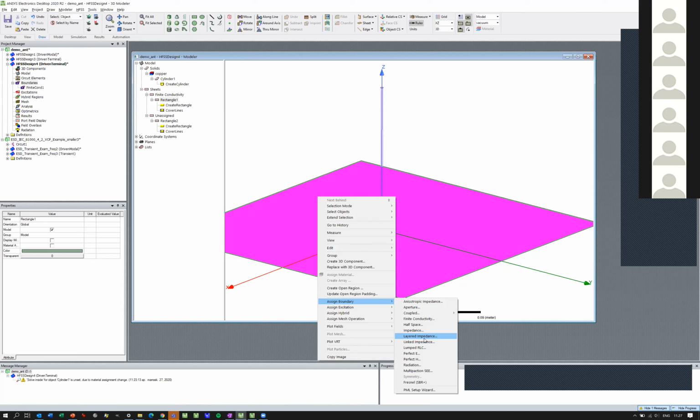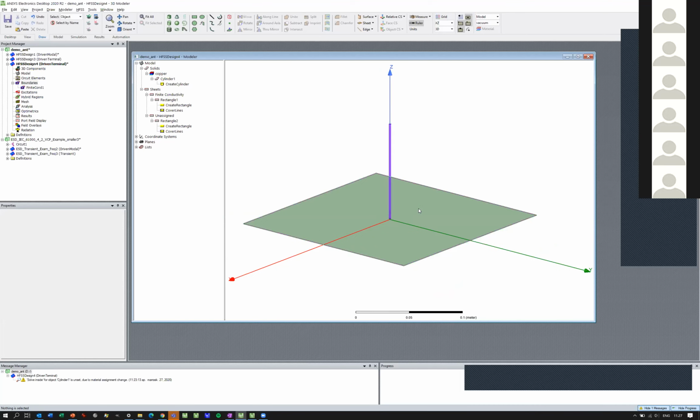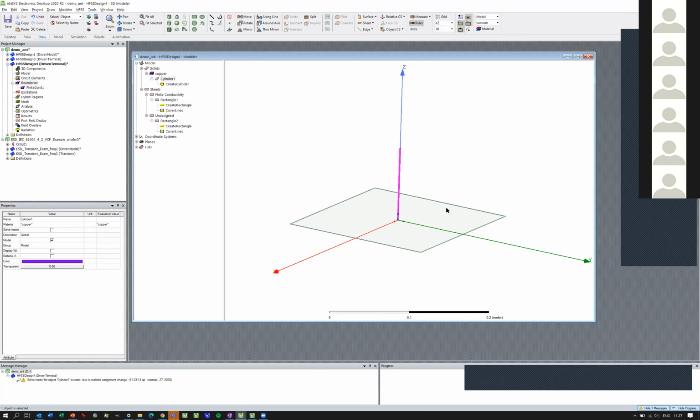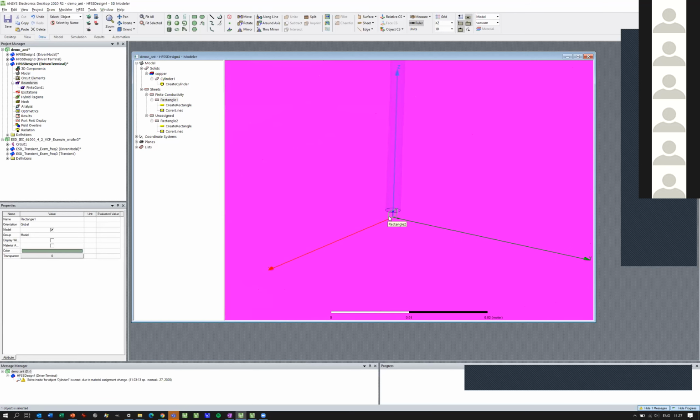And for 3D material, you can use both. You can use volume conductivity and surface conductivity. It can also be different because many times materials are coated, like aluminium. You can have oxidation on the surface of the aluminium. So it's a good insulator in that case, with low voltages. With high voltages, the oxidation on top of aluminium will actually break through, and you have almost full aluminium conductivity. So basically now I have specified my two CAD objects. Oh, actually, there's three because I have this small sheet as a third one.